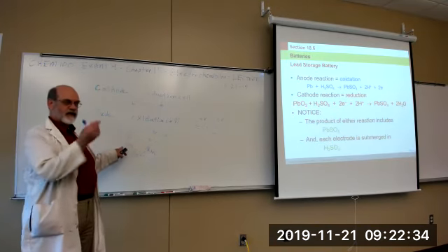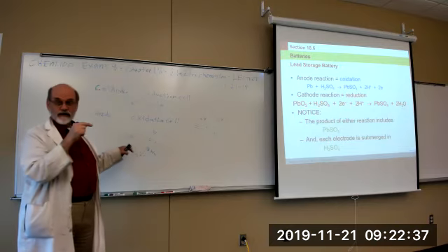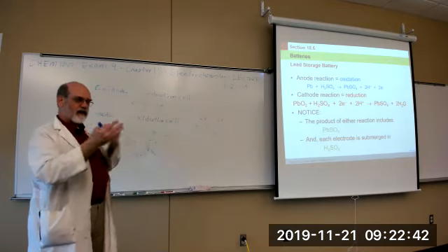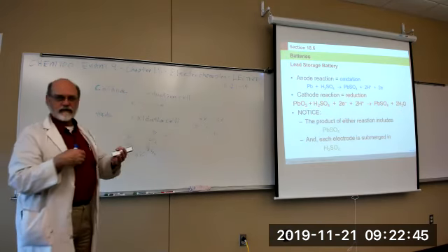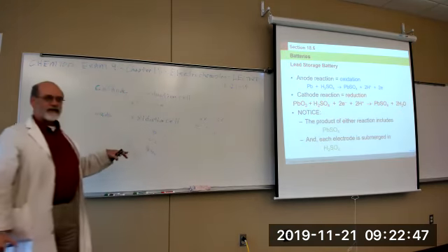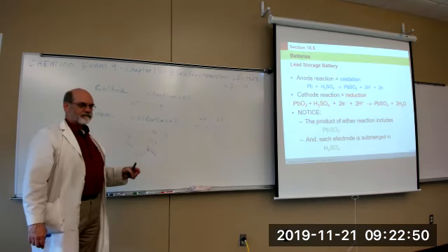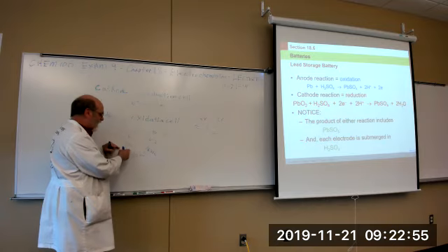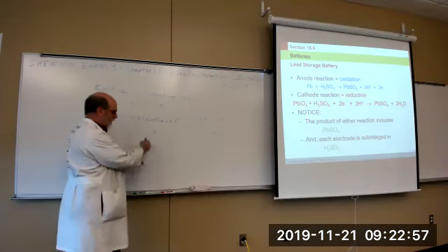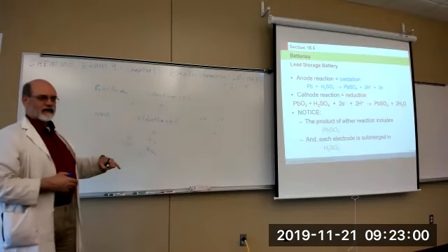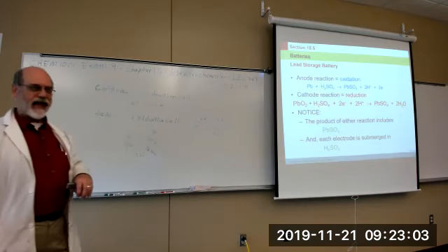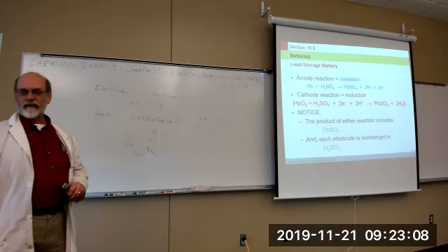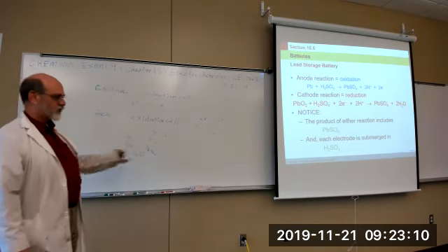So the reaction takes place at the surface of the solid of lead sulfate, and through several hundred or thousand cycles of discharge and recharge, you get this lead sulfate built up on your plate. Eventually, you get so much built up that the solution no longer has access to the lead underneath and the oxide underneath of that one. At that point, your battery's dead. It cannot be recharged, and it's said to be sulfated out. The only thing you can do is replace the battery, send that one to be recycled.